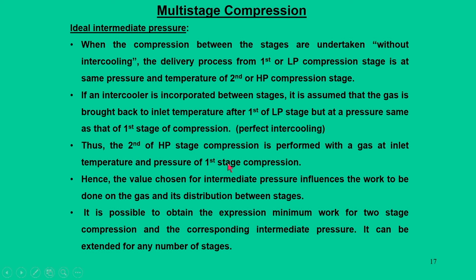Through intercooling, what happens is that when the compression between the stages is undertaken without intercooling, the delivery from the first stage or LP compression stage is at the same pressure and temperature as the second stage or HP compression stage. But when an intercooler is incorporated between these stages, it is assumed that the gas is brought back to its inlet temperature after the first or LP stage, but at the same pressure as the first stage compression. So, this is a case of perfect intercooling.